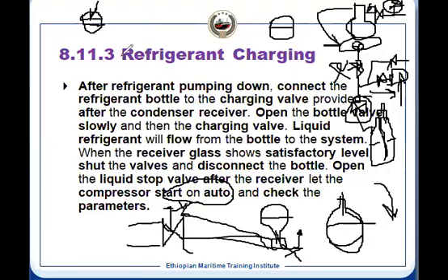When we say the correct level of refrigerant, according to the sight glass inspection, which one is recommended? I mean the correct level when it's collected after pump down, or when it's running in normal operation? When it is pumped down, there will be a level. After, for an example, we are not charging, we are pumping down, there will be a level. And when you are using, that time there will be a level. But both have to be visible.